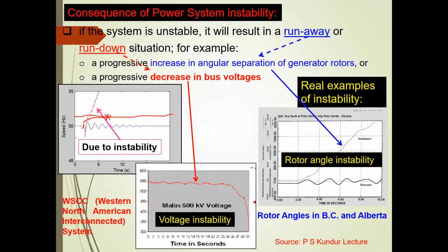Similarly, it happens with the under frequency relay. Let's say you have a lower limit defined, and the frequency dips, and you are not able to regulate your generator, and there is a continuous dip. Then at this instant, the frequency deviation crosses the lower limit. Then again, the under frequency relay will operate here. But you talked about the time, right?